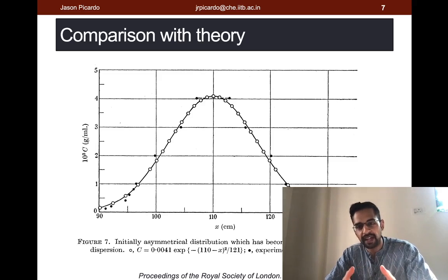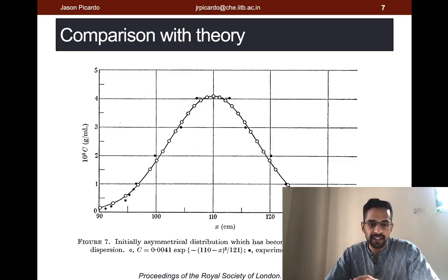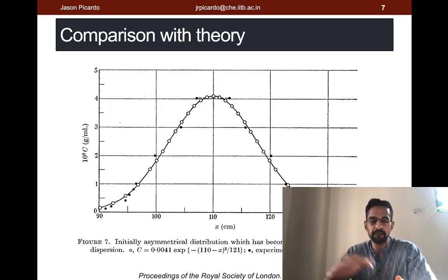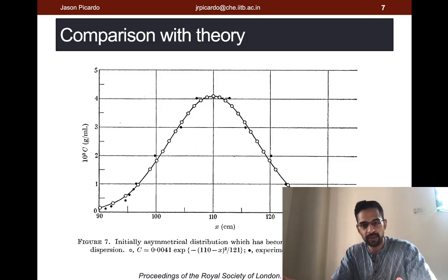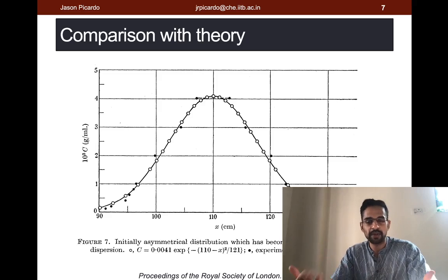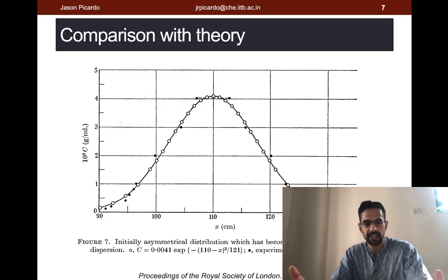And so to determine that and to model that and to optimize that, we don't need all the spatial temporal information that we would obtain by solving the full equations in a CFD solver. But yet in traditional techniques, we have to go through that process. We get more information than we need by solving the full PDE numerically, and then we subsequently average to analyze, right? Because it's difficult to analyze or optimize using all the information that we get.